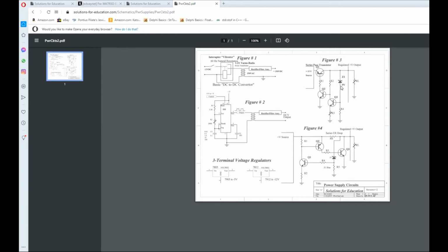First of all, the Zener diode here is like the tie bar on your car between the left wheel and the right wheel. So if this moves up an inch, this one moves an inch. Well, let's talk about volts instead. Let's say, for instance, this is a 9-volt Zener, and this resistance right here is picked to get this in the linear portion of the Zener. The idea is that if this voltage here changes and goes up 20 millivolts, well, guess what?